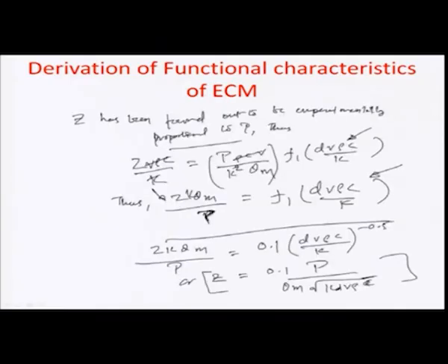So, that is how you can equate z with respect to the various dependent parameters: the beam power, the depth of melting temperature, the k value, thermal conductivity of the material, the beam diameter, velocity, density, specific heat, and so on and so forth.